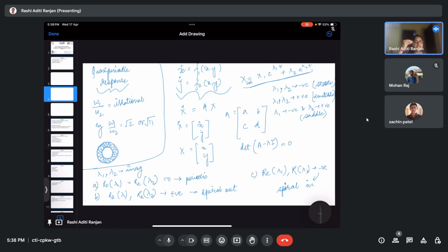Now, my e to the power something negative times time is going to go to zero when my t tends to infinity, right? For t equal to 10 or 20 or 30, it is going to have some small value. It is never going to go to zero, right? So that is why it is stable, but precisely, it's an asymptotically stable system. Understood? Yes, madam. Thank you. However, it would again depend upon the value of lambda. If my value of lambda is 500 or 600, in that case it is going to settle very soon.